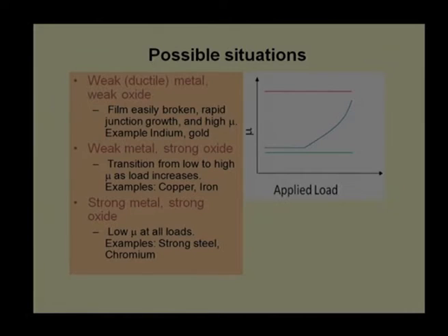That layer is always appreciated. Whenever we design any tribo pair, we should aim for this kind of layer, so that we can get a low coefficient of friction. However, if we want a high coefficient of friction, then we can choose the first case, but in that case the wear rate will also be very high, and then we need to provide appropriate action or appropriate tools to get a solution.